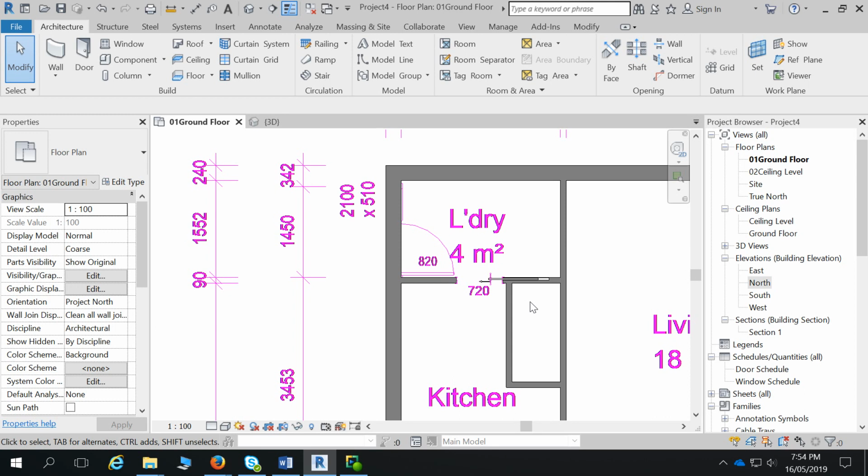You haven't got a wall there, so that wall needs to come. You just scan and miss the wall there as well. Just select the wall, go on the other side of the wall, and drag that blue dot into the other wall. Then you can just create another wall there. The doors need to go on the host, and there's no host where the thing is. So that's okay.